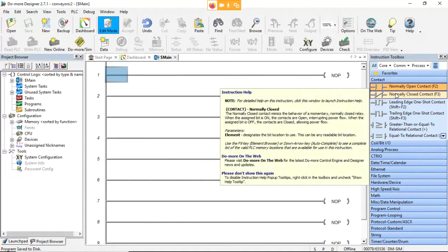Typically we do our stop buttons wired as normally closed. And so when we do the ladder logic inside the Allen-Bradley PLC, or maybe even this one, we actually use a normally open contact instead of normally closed. However, with this simulator, if we do that, we have to remember to click it closed every single time. So as I've been messing around with it, I've decided I like to do the stop button as a normally closed contact.